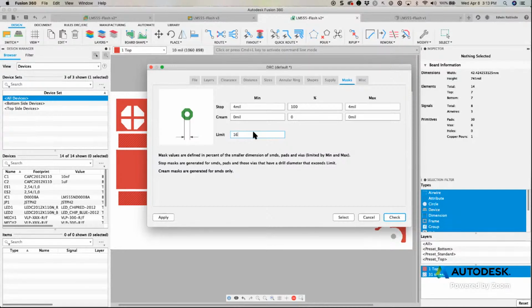Correct. Basically, in very, very dense layouts where you still have lots of vias, there's a lot of potential for shorting, especially in a manufacturing context, where if you have solder paste near these vias and it touches, then it'll draw solder away. So in those situations, tenting, as this process is called, where vias are covered so that you can't solder to them, prevents the shorts and makes the board more reliable. So that's where this value comes into play.